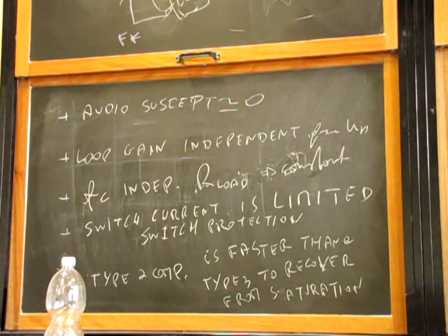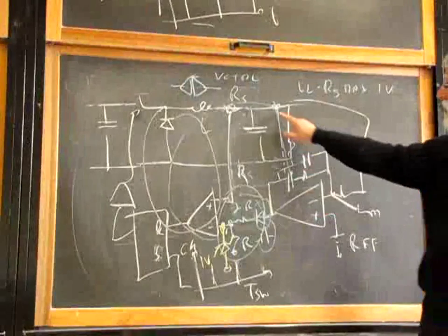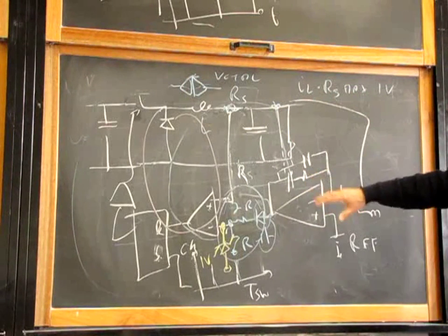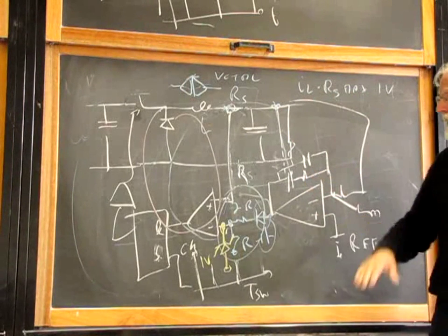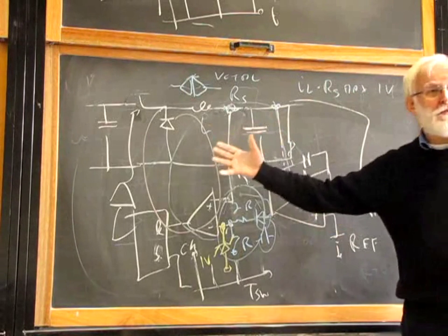When you saturate the system, because for example you are asking for a very large current suddenly here in the output, this current cannot come from your inductance, because inductance has a slow di/dt, depends on the voltage. So this compensator sees the output voltage going down, starts to panic badly, and goes to the maximum. But it saturates, because the system is not responding.